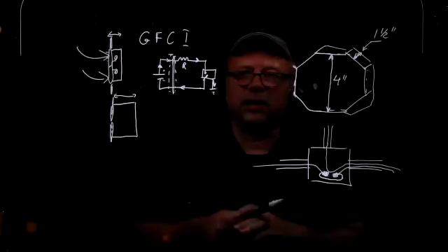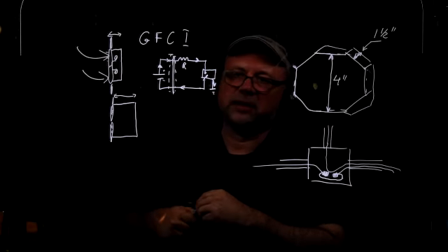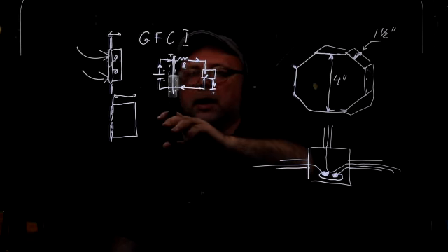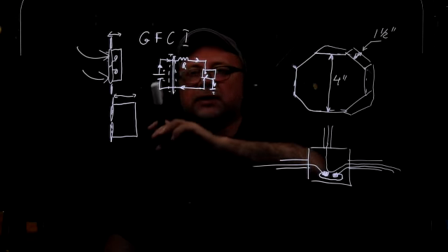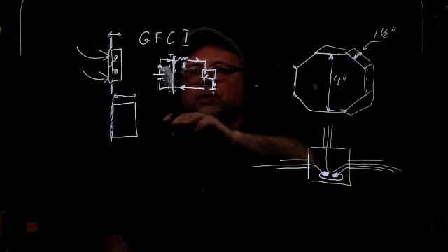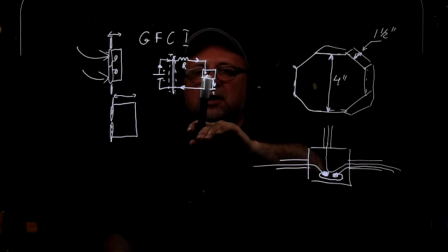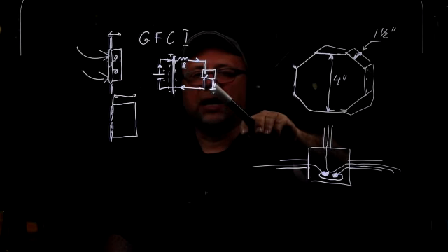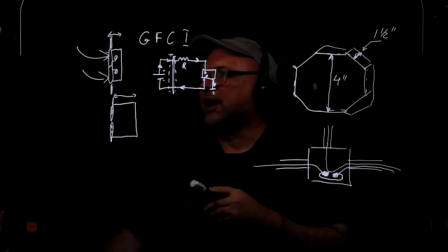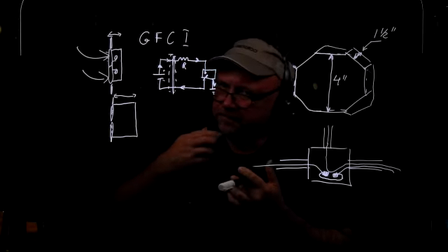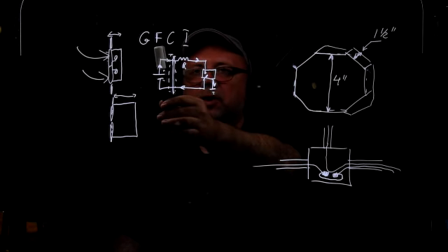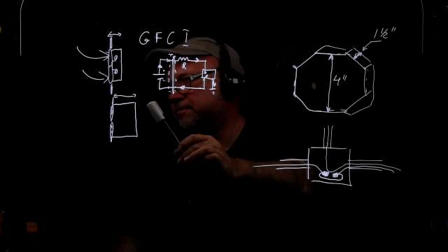There should be no escapees. There should be no alternative paths for the current. If there is, then there is something wrong. Excuse me. And that is going to react and shut down. So if something happened here and some of the current escaped to the ground, we would have something that's called a ground fault. Okay? So ground fault. Upon the ground fault, the circuit will be interrupted.